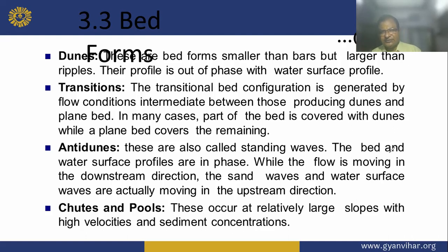Anti-dunes, also called standing waves. The bed and water surface profile are in phase, and while the flow is moving in the downstream direction, the sand wave and water surface wave are actually moving in the upstream direction.